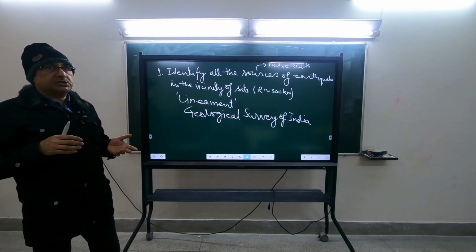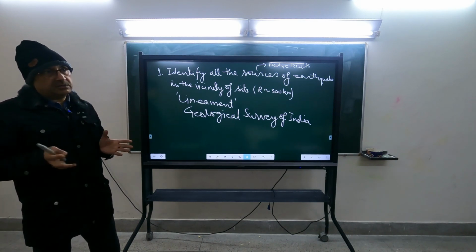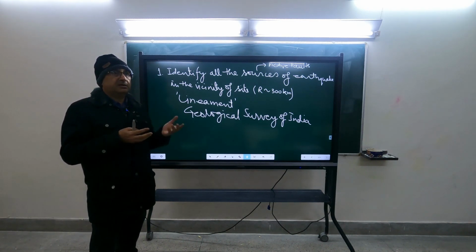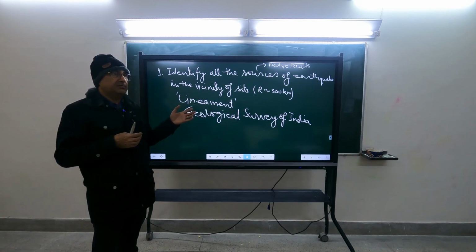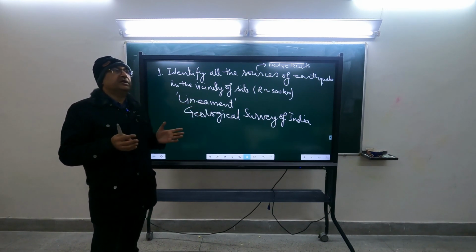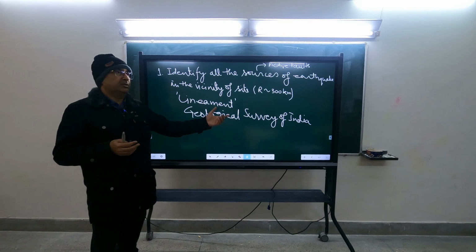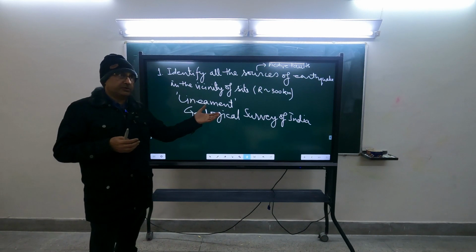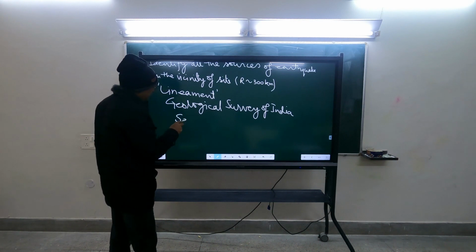Then during earthquakes, the Geological Survey of India conducted surveys of those earthquakes. It plotted the subjective intensity, using different scales: MMI, MSK, EMS. EMS is relatively recent, it was not there, so the MSK scale was used. Using MMI and MSK scales, they plotted maps of earthquake intensity. And slowly they became involved in the study of faults also, and so it has what we call a seismotectonic atlas of India.